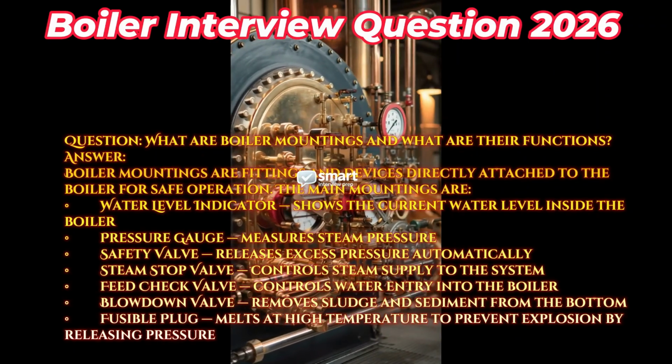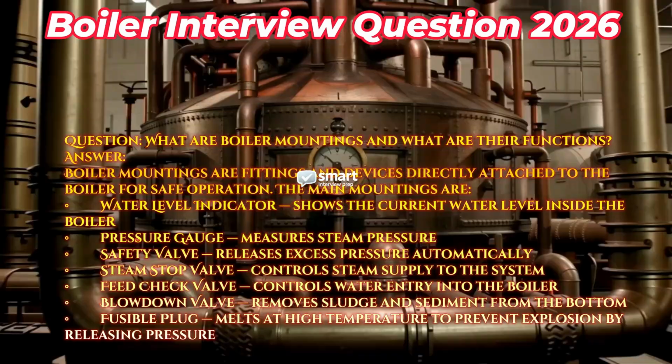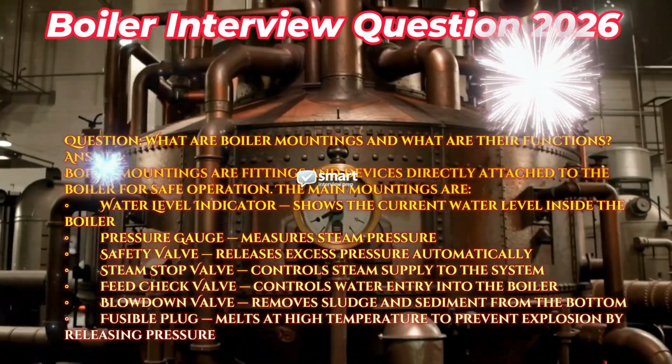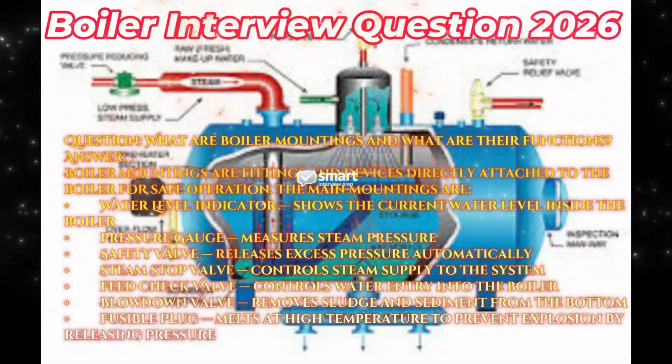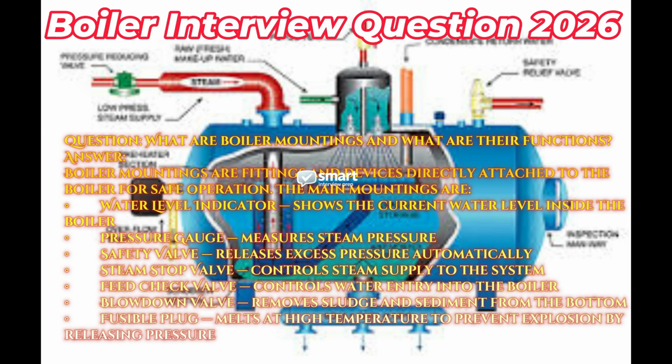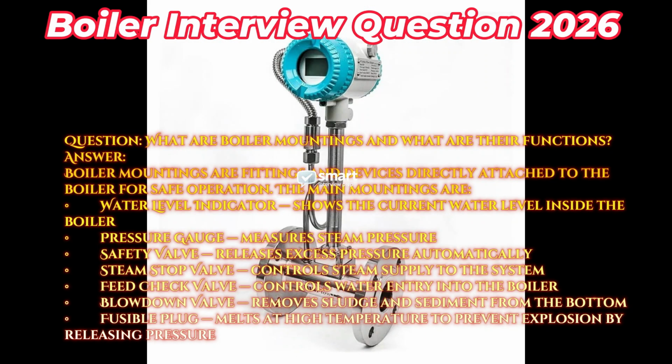Feed check valve controls water entry into the boiler. Blowdown valve removes sludge and sediment from the bottom. Fusible plug melts at high temperature to prevent explosion by releasing pressure.